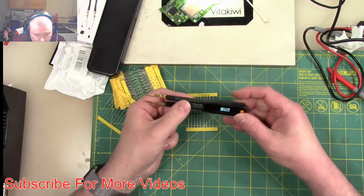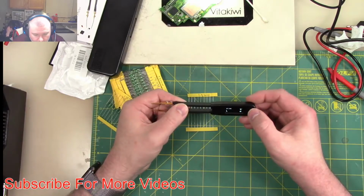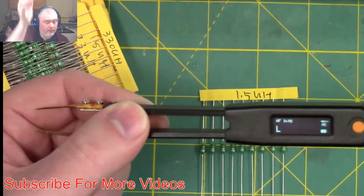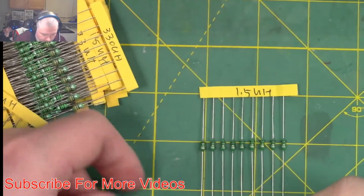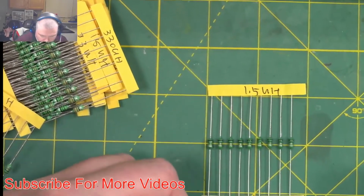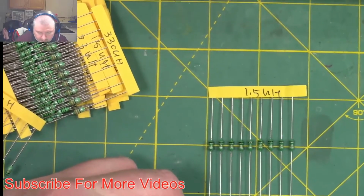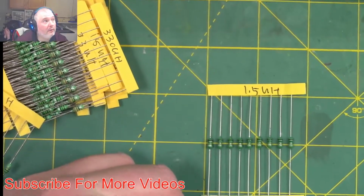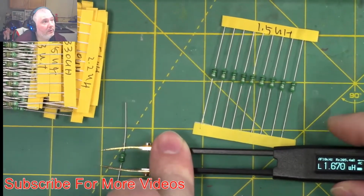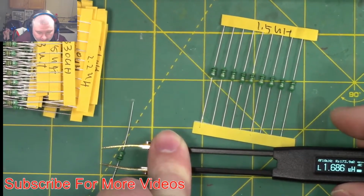We're going to turn this on, and we're going to set this to inductance, which is L. Inductors on a board are labeled as L. If I touch these two leads here like so, I should get 1.69, so it's a little off here. Oh, you can't even see that. There it is. So I'm getting 1.6, and it's 1.7, and it's supposed to be a 1.5 microhenry.